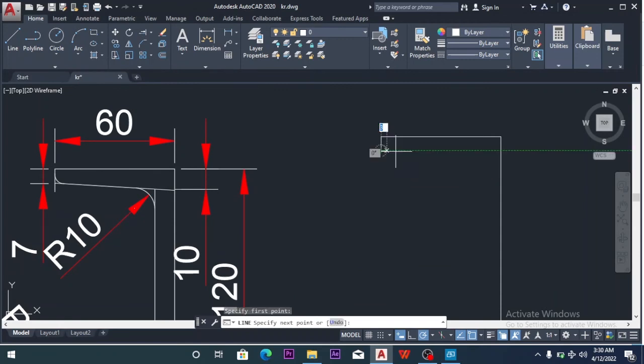So I click on this. Remember I'm going a distance of plus 50 in the horizontal direction, and in the vertical direction I'll go in minus 3. So for me to use the relative coordinates to draw this, I have to type in my 50, which is on the x-axis. Remember, the x-axis comes first. Then on my keyboard I tap comma.